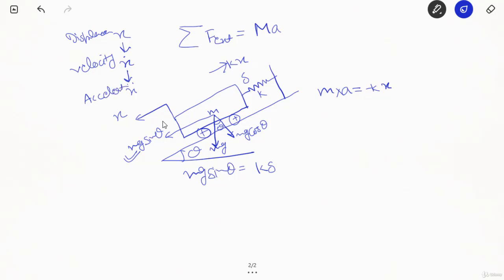In most books, you would find the acceleration notation in this form, so do not get confused. Now, replacing this symbol in this equation of Newton's second law applicable to this system, this will become m x double dot plus kx equal to 0, right? So this is the governing differential equation for the situation we have shown in this figure, right?